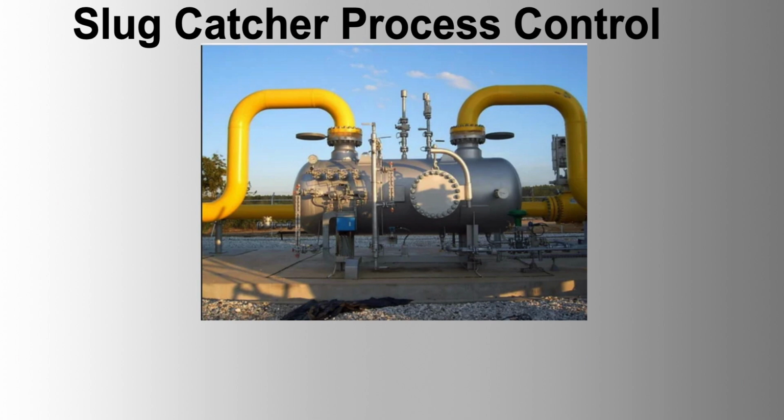Conclusion. Implementing advanced control algorithms such as MPC, adaptive control, and cascade control can significantly enhance the performance and stability of slug catcher operations in an onshore oil facility. By combining these algorithms with robust instrumentation and continuous monitoring, the process can be managed effectively in steady-state conditions, reducing the need for operator intervention and minimizing the risk of emergency shutdowns.